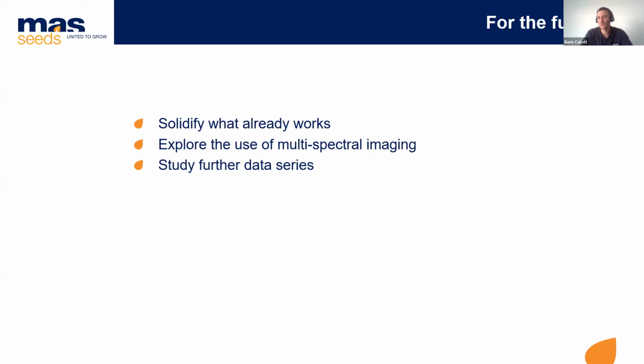And then we still have an exploratory part, which is the interesting part also. So now we have multispectral imaging, thanks to Mavic 3M. There's a lot of data, right? For a normal field that could be 10 gigabytes for a flight at 20 meters with the RGB camera. It will be 50 to 60 gigabytes for the same flight with the multispectral camera. So it's a lot more data. See what's worth it, what's not worth it, and how to use it. So we'll see about that.